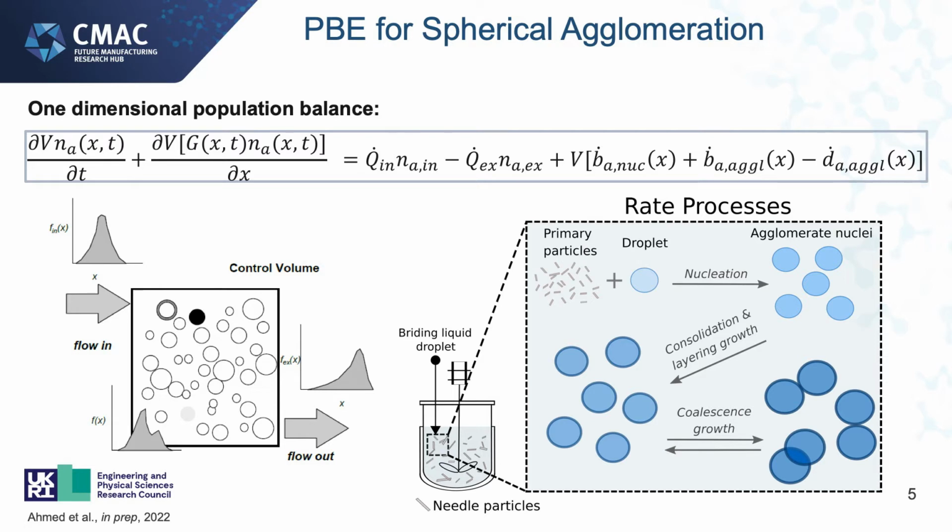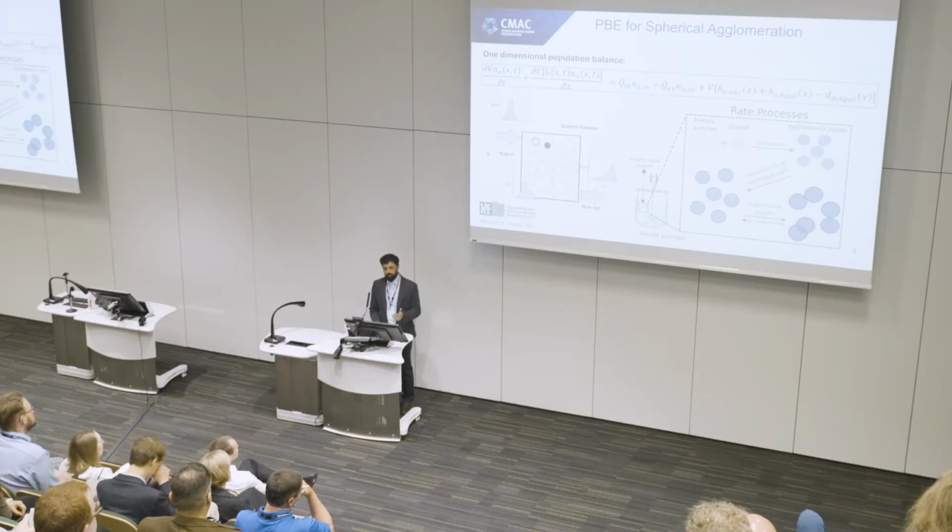Okay, so one of the tools that we can use for our predictive and modeling strategies has been the population balance. This has already been applied quite extensively now to crystallization, and I know there were some examples shown yesterday. But essentially, we can apply this tool to any particulate process involving the transformation from a liquid to a solid or from a solid to solid. And we can do this by defining our control volume. In this case, we can also refer to it as our particle generator. And by specifying your inlet size distributions and your key rate processes.